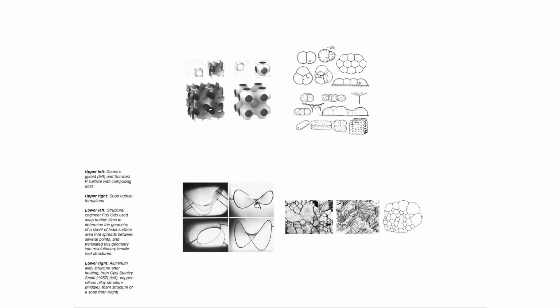These are investigations done by Otto, from the Institute for Lightweight Structures in Stuttgart. I think I mentioned him already last time. So he was doing these analog experiments where he would have just a steel wire, which represents this kind of boundary, and then he would span these soap films between them. Again, a soap film acts a little bit like a stocking, okay, because in a soap film, the soap just has tensile forces, so it's trying to basically squeeze itself into a point.